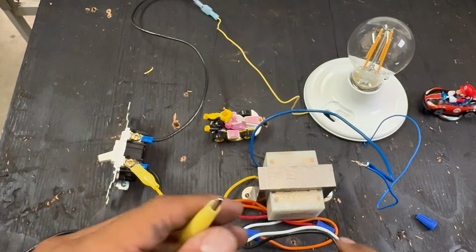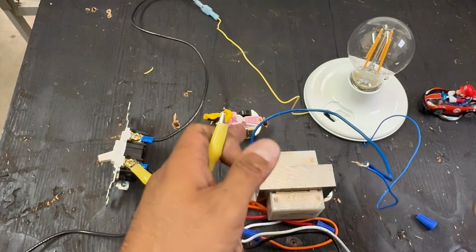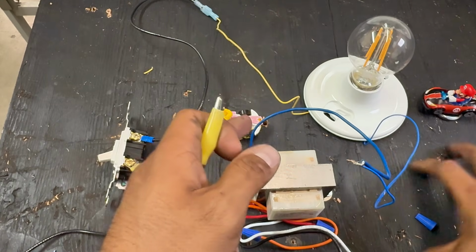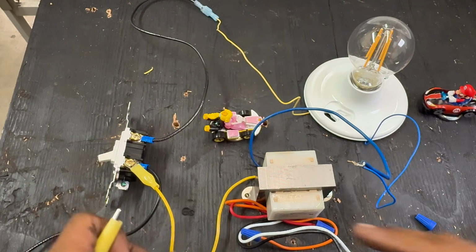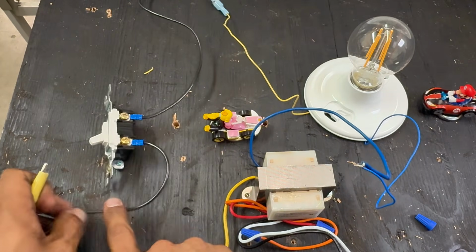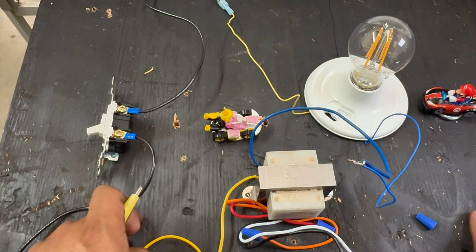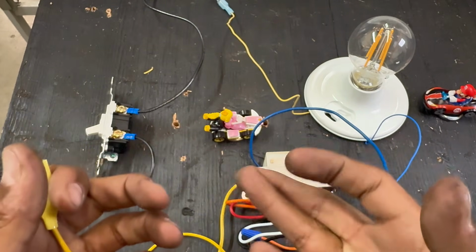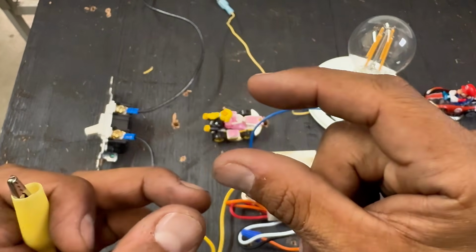So typically, and we can kind of go over it briefly, on my common, this is also grounded, and just pretend this is wood, but just pretend it's metal, okay? Just for a minute, guys. Pretend this is metal. So typically the common is grounded to this because what happens if this wire here, the one that's carrying the 24 volts, touches the metal? Well, it's like the metal is touching the common because it's grounded, but it's to protect you, it's to protect itself, and it'll usually trip a fuse.